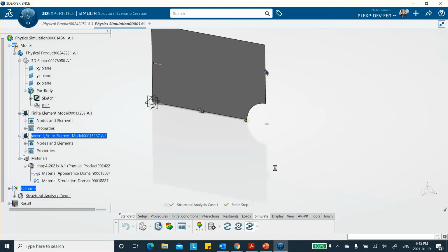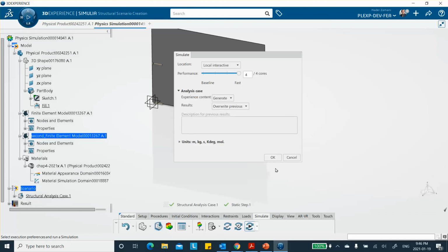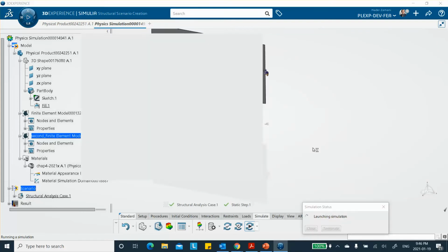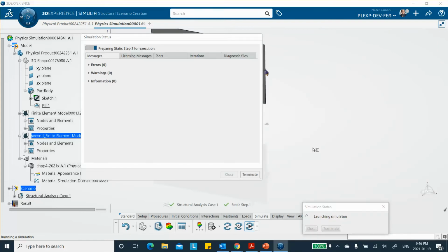Of course, I'm using linear triangular element. It was better to use quadratic triangular element, but in the book, because I want to make a table and compare all these together, I started with linear, and therefore it's staying in linear. I'm sure we're going to get the same warning message there, but that's okay.